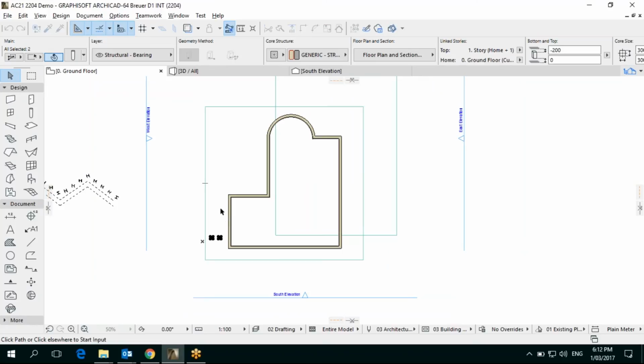Previously, it would always detect surfaces as well, but this was causing unnecessary detection. So now if you press space, it will then start detecting the boundaries based on the surface. Similar to Magic Wand, when you press spacebar, it will detect the surface. Automatically it's by edge, but if you press spacebar, it will detect the surface.